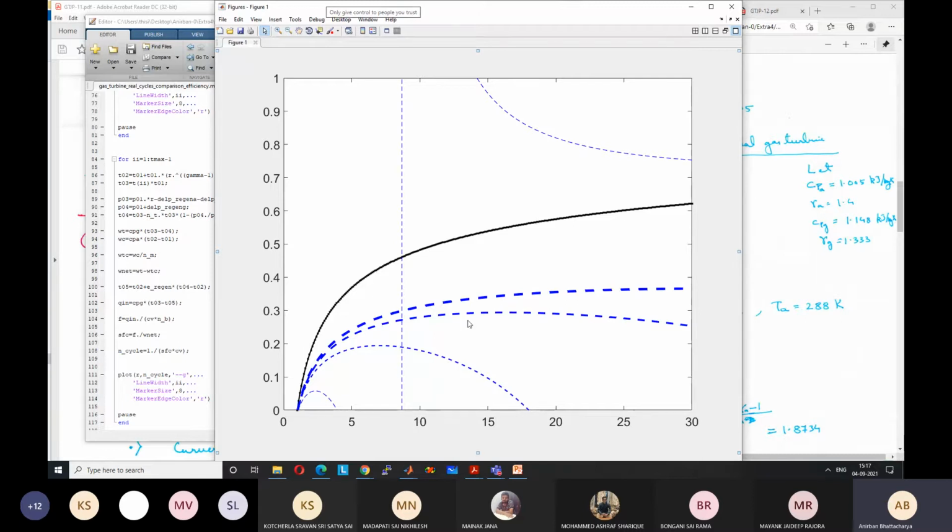However, if we increase the temperature of the turbine inlet, there is more work output available from the turbine, because now we have a larger delta T in the turbine for gaining work. So relative to the work output from the turbine, the losses become less significant. So as a result, for larger value of T, we still get quite good efficiency.